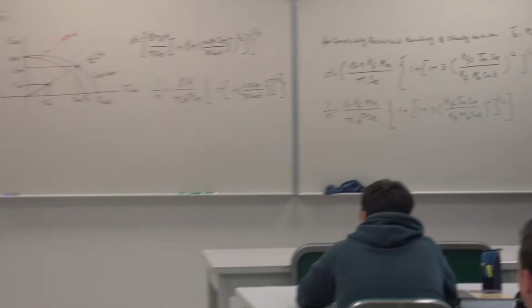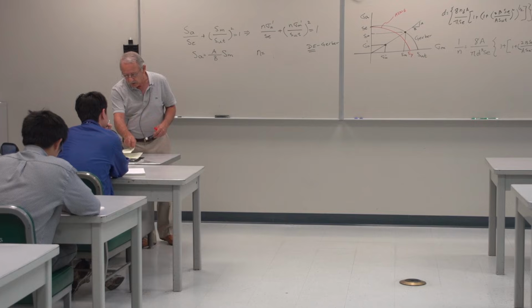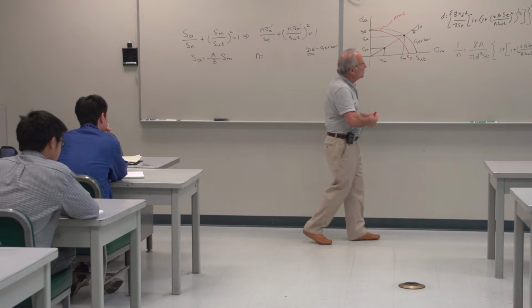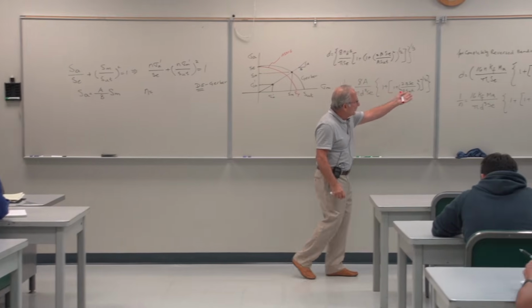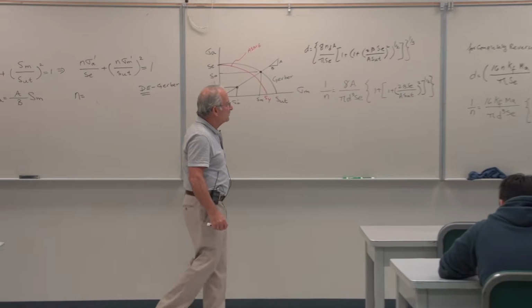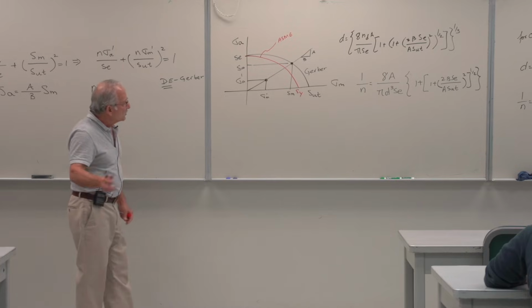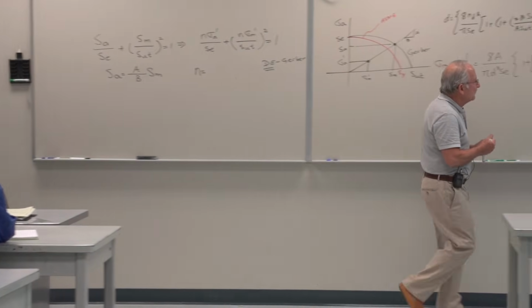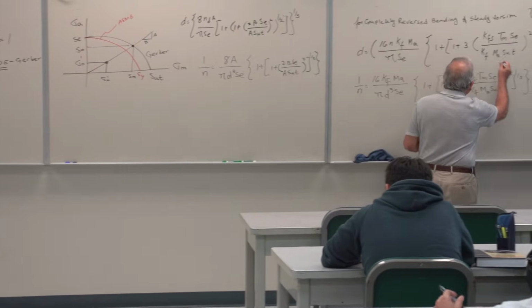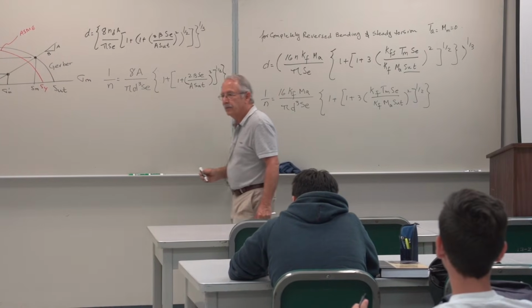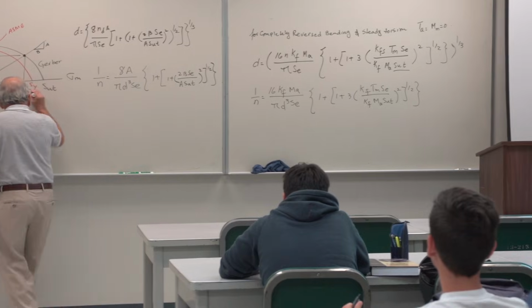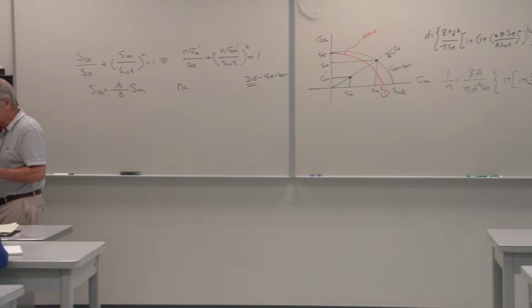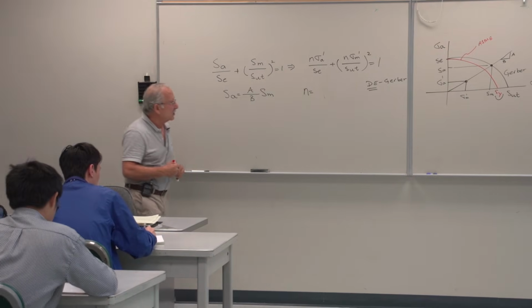So these are the equations, including that for Goodman. This is the equation for the Gerber criterion. The ASME, the elliptic is also there. One sign, of course, is if you see that and it's a nonlinear equation, it's probably Gerber. If you see this and it's a nonlinear equation, it's ASME. Now you might say, well, we could use a linear equation too.